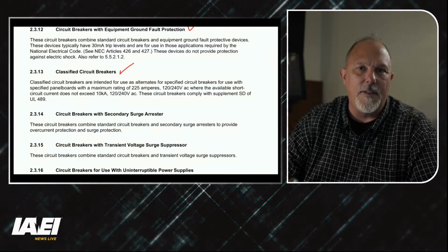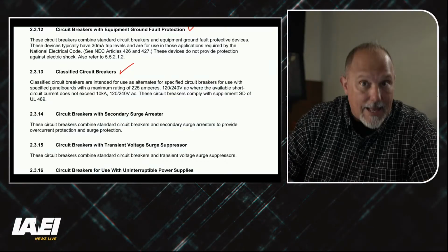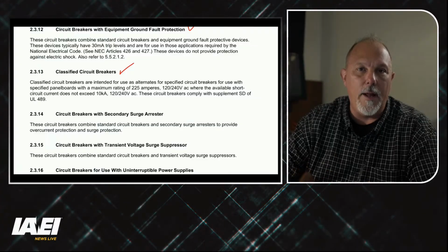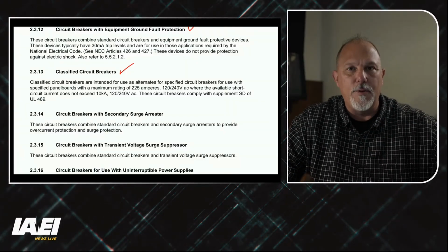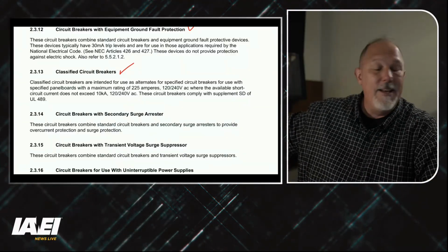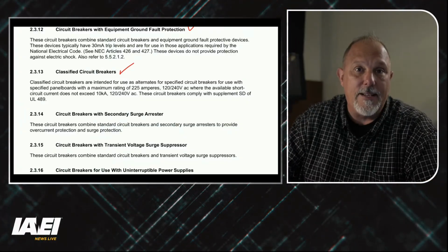This one fits all of these panel boards, and it wasn't classified. And I made this statement. I said, oh, no, you can't do that. You need to find out what is the brand of the panel board that you have and make sure you buy the right breaker for that panel board. The individual was very happy and said, I'll be back.